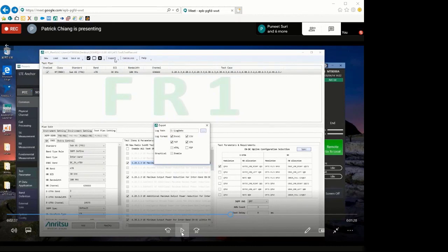Usually the temperature chamber should accept GPIB commands, right? And then this should be simple. You set it to like 40 degrees Celsius, or you set it to 0 degrees Celsius, by just one single IP command. Then in our ATS GUI, we allow you to insert the GPIB command, so you can control your chamber. Yeah.